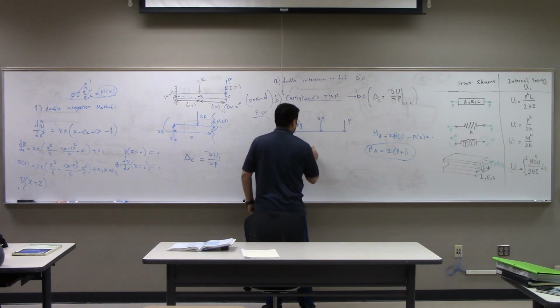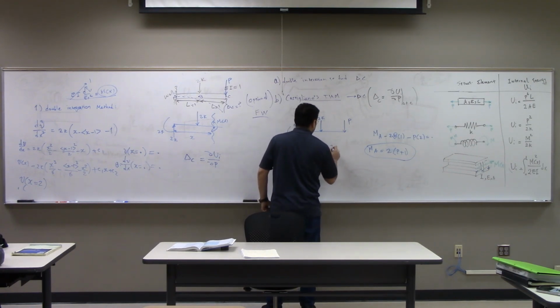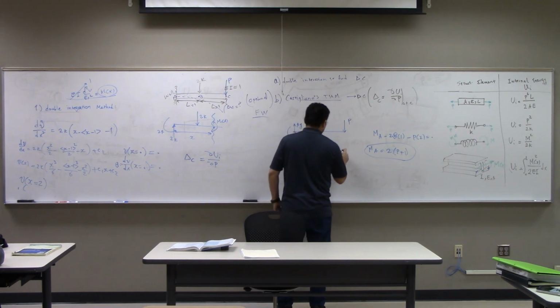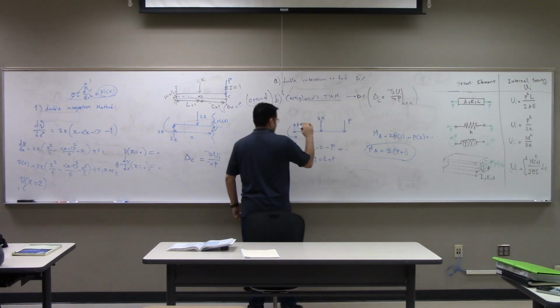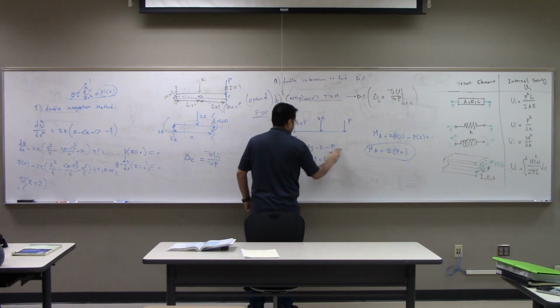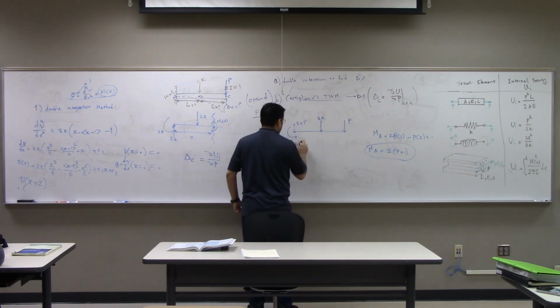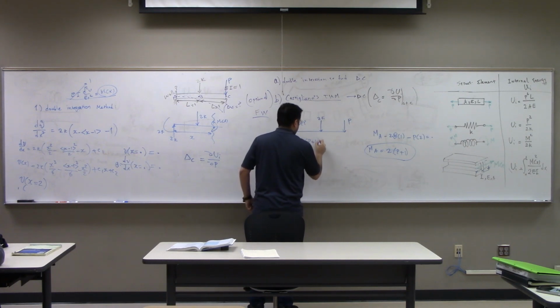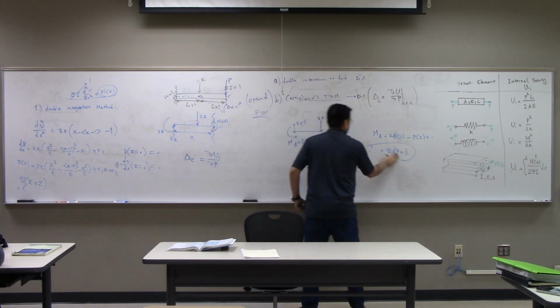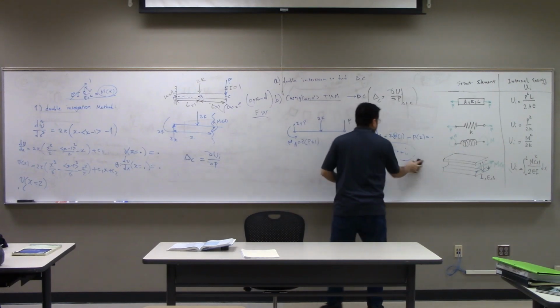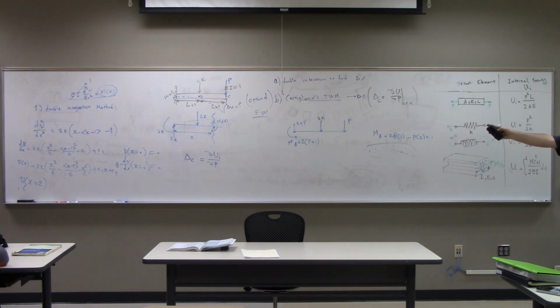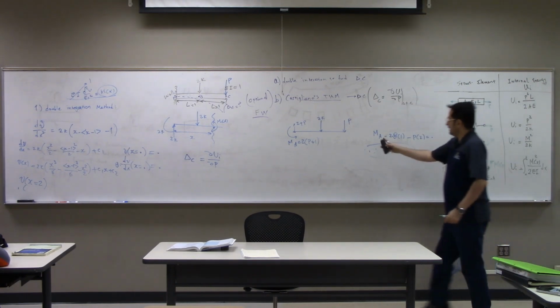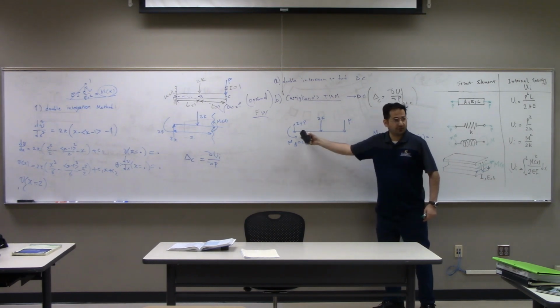And AY minus 2 minus p is equal to 0. So you get AY is equal to 2 plus p. So here, put 2 plus p, and MA, put 2 times p plus 1. Now, this is your FPD for arbitrary p. Don't forget, we don't fix p to a value. Why? Because we want to take derivative. It should be like a parameter. So my arbitrary p will show up at the support reaction.